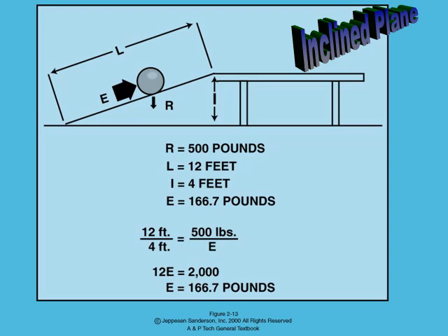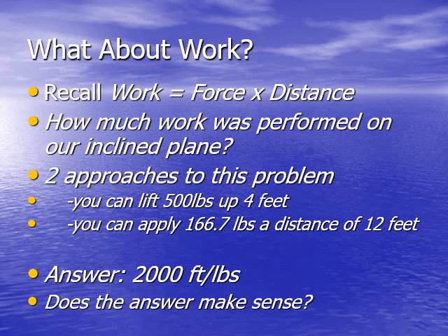An inclined plane allows us to move loads vertically with reduced force over a longer distance. This principle applies directly in loading ramps and slide-out tool trays used in aircraft hangars and cargo operations. Whether you lift a 500-pound object vertically or slide it up an inclined plane, the work performed is the same, 2,000 foot-pounds. The inclined plane reduces required effort but increases distance. The law of conservation of energy ensures that work remains constant.